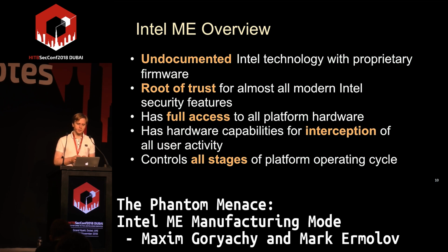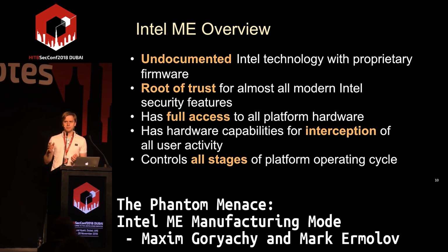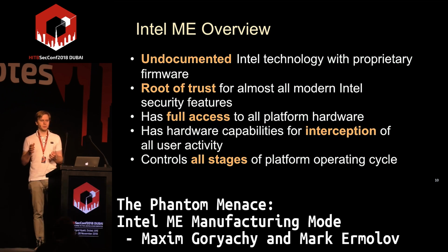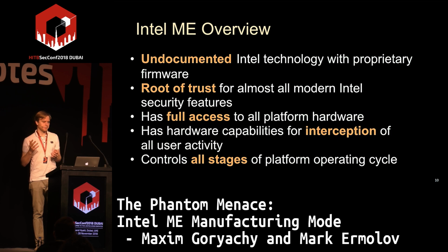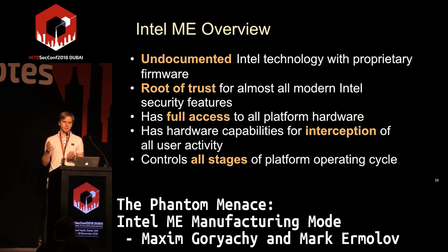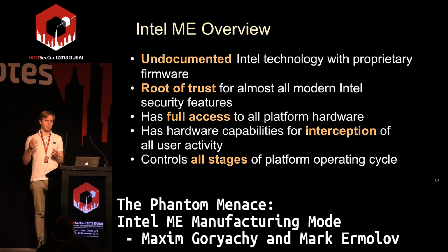Intel has chosen the following design for ME11: an independent x86 core. Really, in the PCH we found maybe 5 microcontrollers. 3 of them are x86 cores, and 1 is an ARC core.